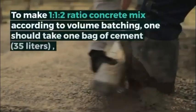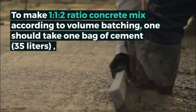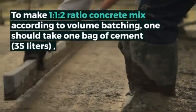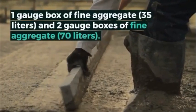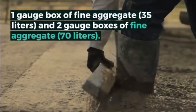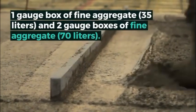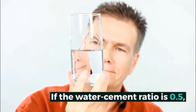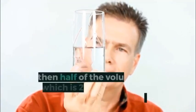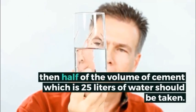To make a 1:1:2 ratio concrete mix, according to volume batching, one should take 1 bag of cement, 1 gauge box of fine aggregate, and 2 gauge boxes of coarse aggregate. If the water-cement ratio is 0.5, then half of the volume of cement, which is 25 liters of water, should be taken.